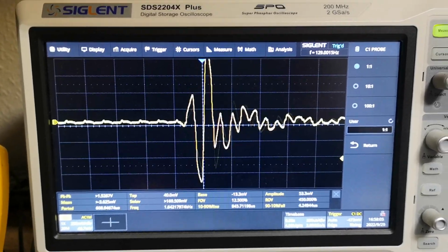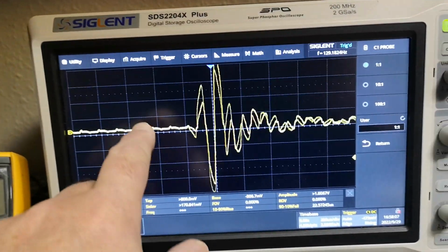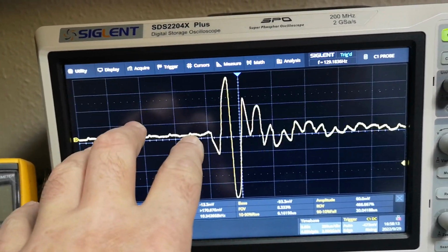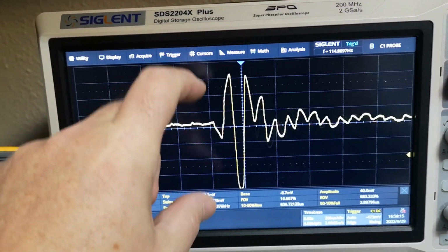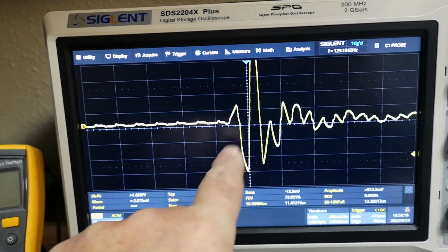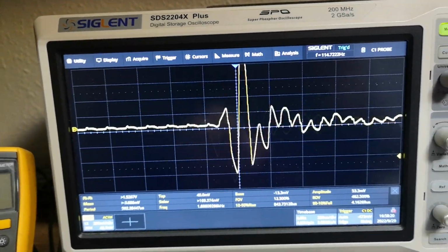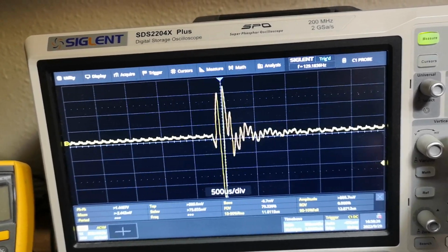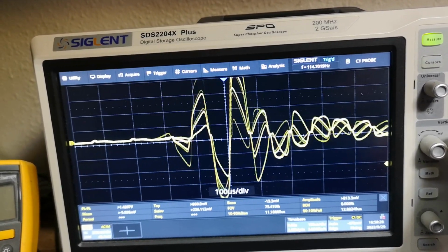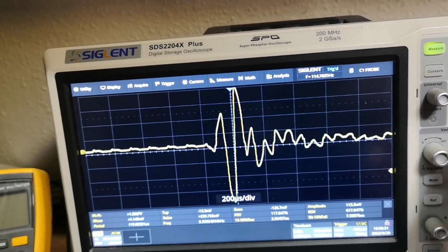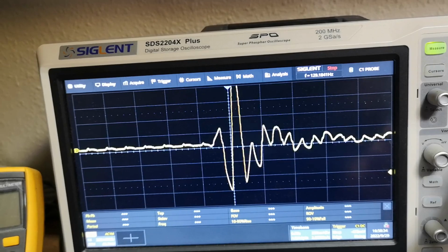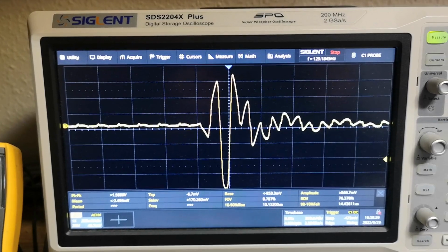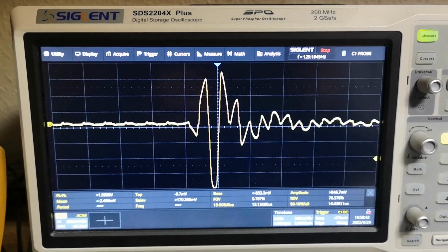So now let's look at the pulse after the modulator. So this is the about 8 kilohertz modulation, the carrier, and so the pulse goes to the modulator, and out comes the chopped up pulse, as you can see here. Isn't that fascinating? Depending on how we look at it, it is now made into an 8 kilohertz. Let me see if I get like this, and then single. Then you'll see the pulse is now chopped. That is how it works.